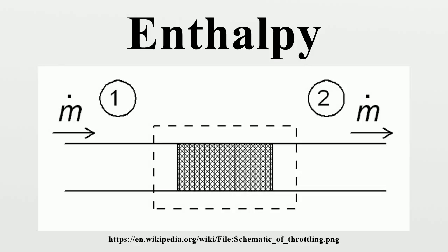The parameter P represents all other forms of power done by the system such as shaft power, but it can also be, e.g., electric power produced by an electrical power plant. Note that the previous expression holds true only if the kinetic energy flow rate is conserved between system inlet and outlet. Otherwise, it has to be included in the enthalpy balance. During steady-state operation of a device, the average dE/dt may be set equal to 0. This yields a useful expression for the average power generation for these devices in the absence of chemical reactions, where the angle brackets denote time averages.